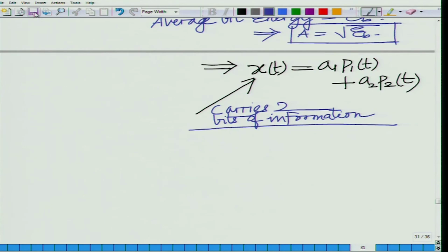Okay. So, similar to quadrature carrier multiplexing, separate bits of information. In quadrature carrier multiplexing, it's an analog modulation scheme. So, separate message signals m1(t) and m2(t) can be modulated on the orthogonal carriers. Here, we are transmitting separate information symbols A1 and A2 on the two orthogonal pulses, that is cosine 2 pi fc t and sine 2 pi fc t.